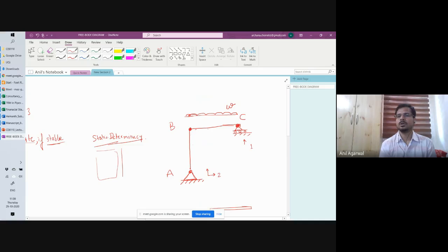I cannot do that because at the hinge, it is different from the rest of the structure. Everywhere else, I have 3 unknowns and 3 equations. So every time I split anywhere else, I get 3 additional unknowns and I get 1 extra part. So I get 3 additional equations. But that doesn't happen at the hinge. So at every hinge, you have to cut. If you don't cut, you are making a mistake. So that first way of a single part cannot be used, but I have to cut here still.